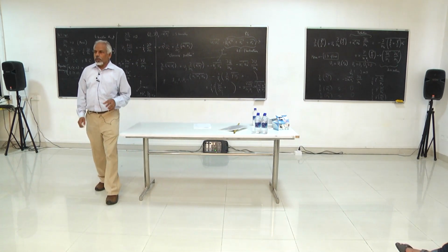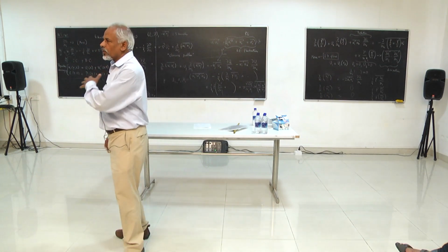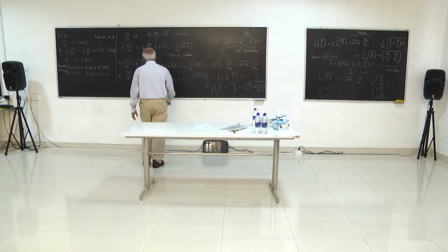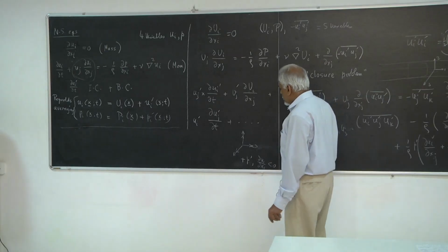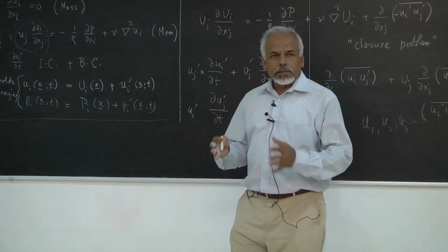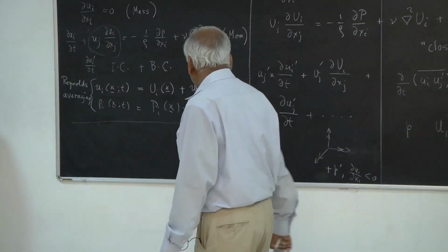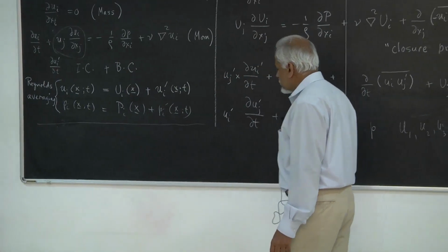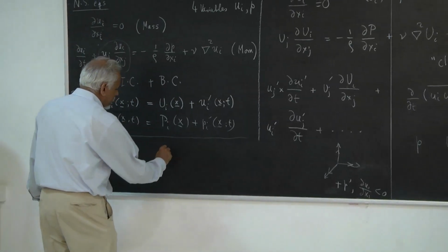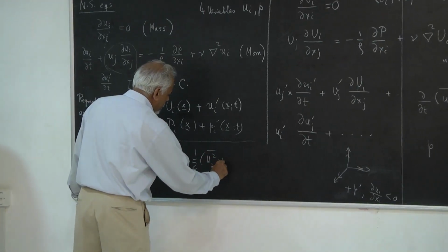I mean, that's as best as I can make it, but I can repeat it. So if you want, you can make it more quantitative in some other cases, but in general, that's the idea. And because of this, you can model it if you want to model it. The pressure velocity correlations, as they're called, pressure velocity gradient or pressure rate of strain correlations, etc. What it will be is its effectiveness is proportional to a difference in kinetic energy in different components. So let's say something like this, U2 squared or U3 squared.